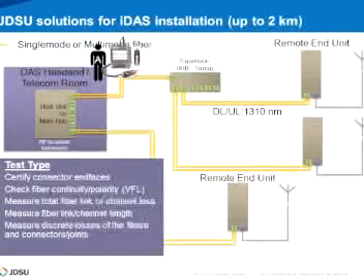So the example of the indoor DAS, which is similar to the cell site deployment, the lengths are shorter. Sometimes you have the pair TX/RX fiber. You can define single mode and multi-mode fiber here, and the procedures of the connector interface, verifying polarity, continuity, measuring optical link loss might be sufficient for the installation, while for troubleshooting, definitely OTDR would be the right tool to determine where the problem may occur.